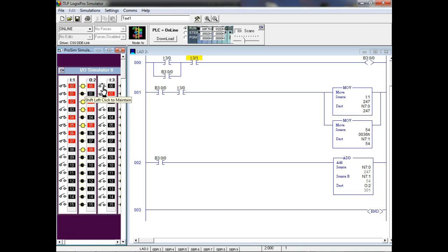This guy's got to be in series with the run. And it could be on the right-hand side of your fill-in, or it could be on the left-hand side. Each input instruction takes so long to scan, and it doesn't make any difference which side you put it on. What I was showing you, if you got into one that was written in Germany, they're going to put the stop on the right of the fill-in. Over here, 90% of the time, they're going to put the start on the right. Unless they learn from German people. So I just want to show you, that stop button could be anywhere. Right? It's just a normal input instruction.